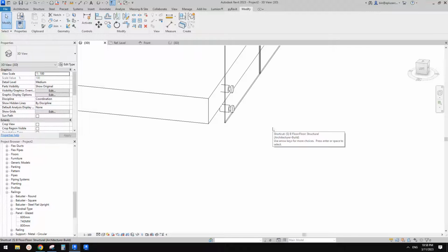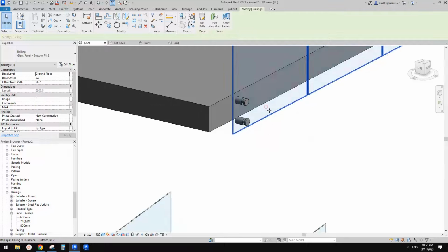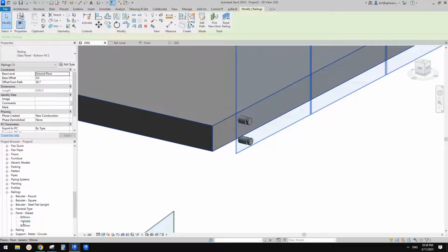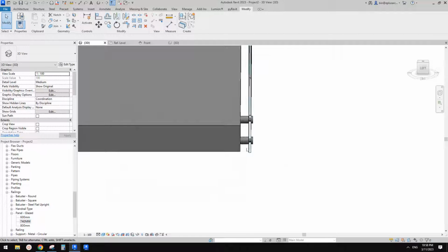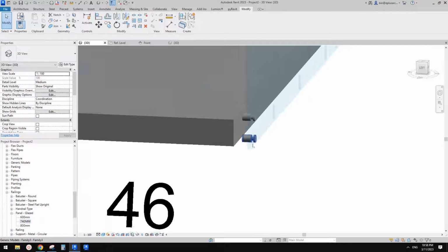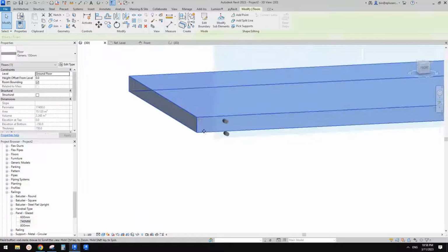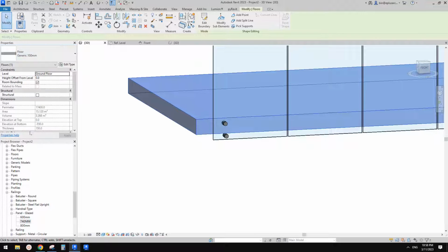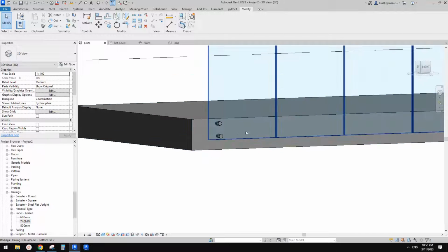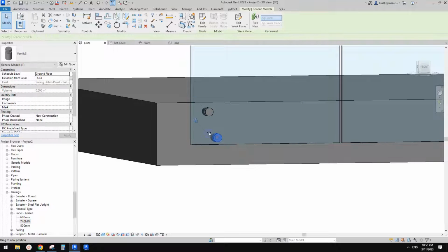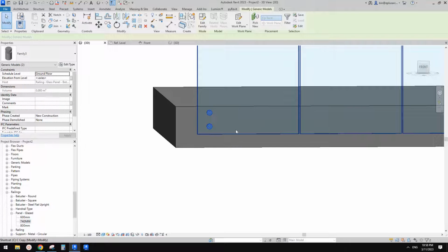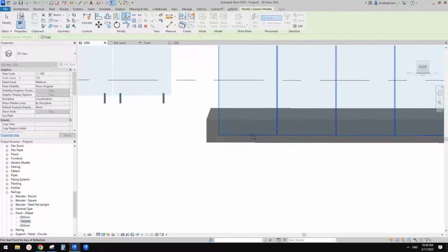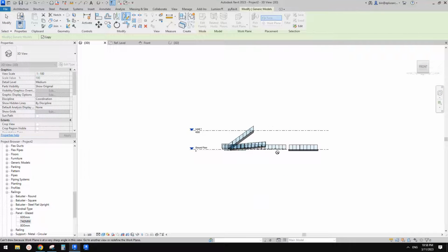Okay, so let's have a look. Maybe I'll change the shade. Okay, so the thickness of this panel is not right, so let's go back here, 740, 12, apply. Okay, so I think that's better. You can see now it's matching the thickness, and this floor is a bit too thin. Maybe change to 300. Okay, I think that's better. And then basically just place. I'll just copy this one down. And then maybe I'll just, or maybe just mirror it. It won't work. Mirror doesn't work.